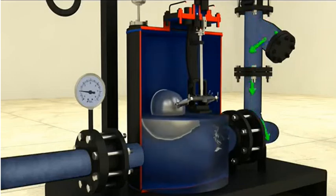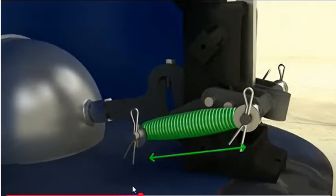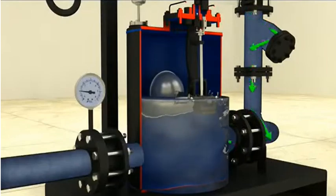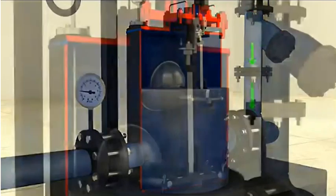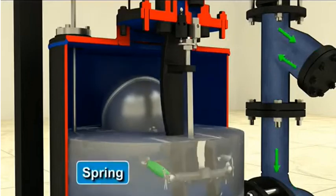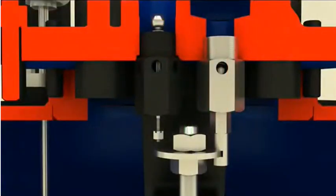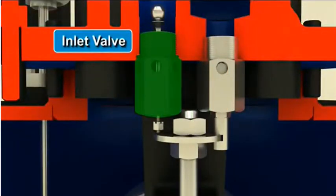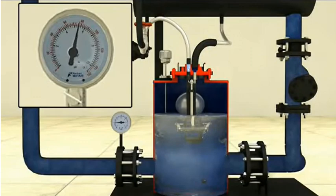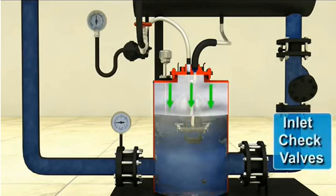The float will become buoyant and it will rise. As the float continues to rise, the mechanism linkage engages, which increases the tension on the spring. As the float rises up to its upper tripping position, the linkage mechanism snaps upwards, releasing the energy of the spring, and it pushes the rod upwards and simultaneously opens the motive steam valve and closes the exhaust or vent valve.